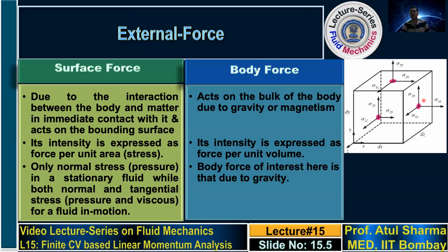Basically, each fluid has a thermophysical property which I introduced earlier called dynamic viscosity, which is due to the stickiness of the fluid. Each fluid has certain stickiness which leads to resistance between the motion of the different layers of the fluid. So when you consider the velocity gradients and the viscosity, there are some viscous forces which act on a fluid control volume.